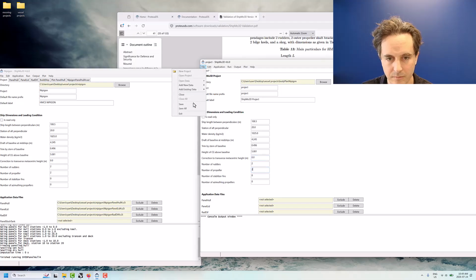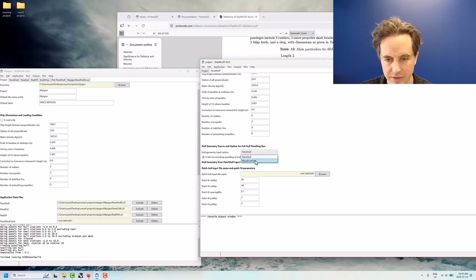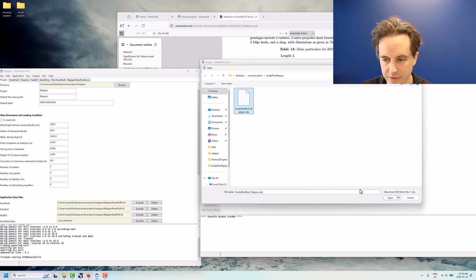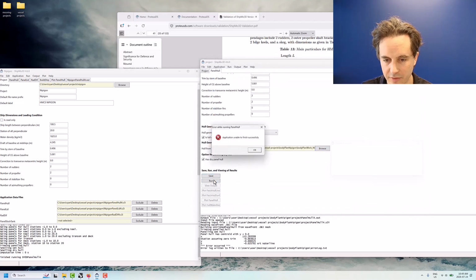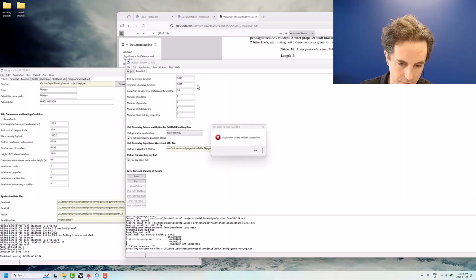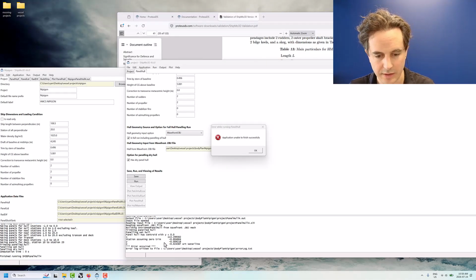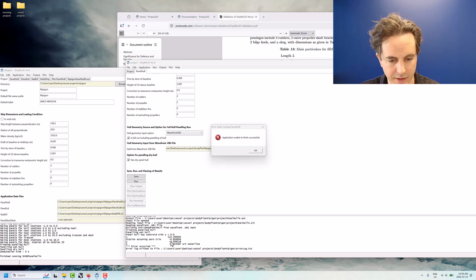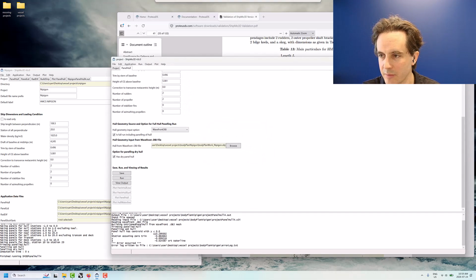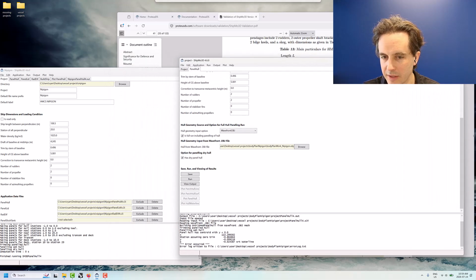Okay, save. So we'll add new data. Panel hull, and we want to do the wavefront OBJ. There's our OBJ file, and we'll go save and run. Okay, so I can see that it's picking up that there's some vertices with an ever so slightly negative Y component. That's kind of the issue here. Sometimes when trimming a mesh and generating a mesh after trimming the surface, you can get a little bit of deviations. So I'll show you how to fix that real quick.